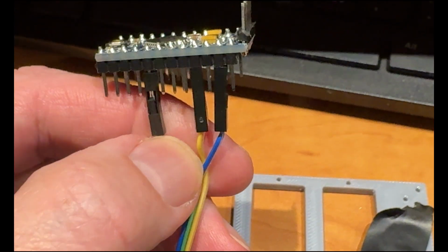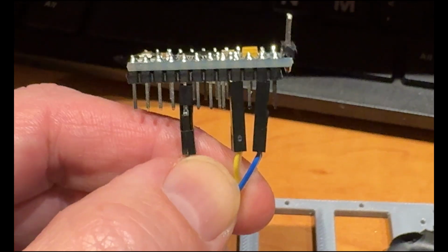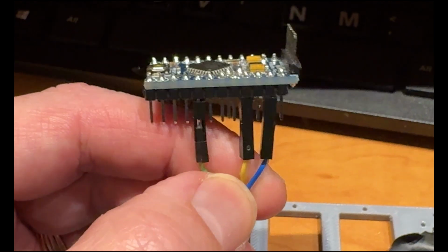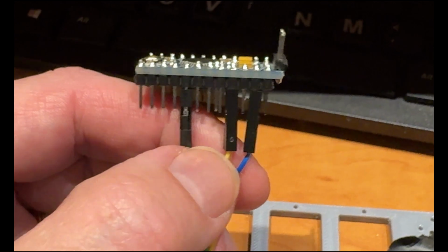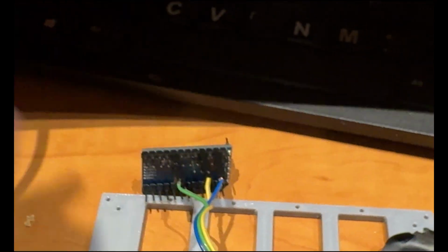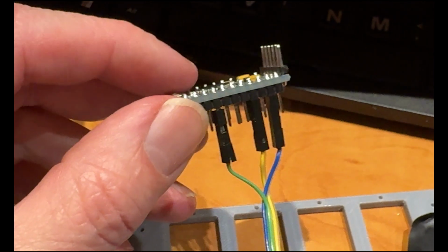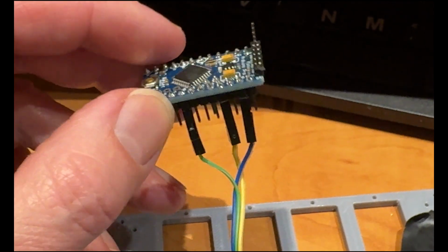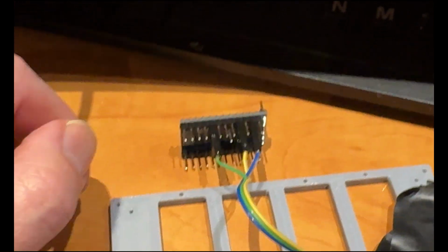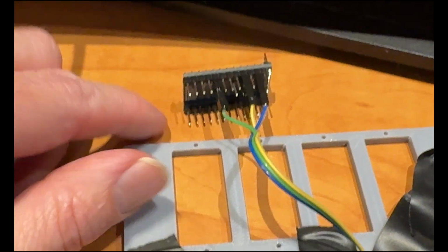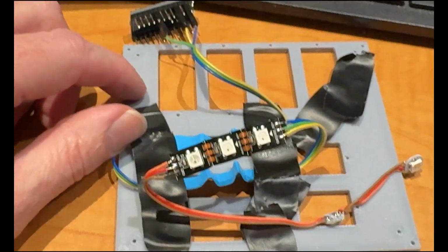And then as far as power, you can get a 4 AA battery holder. AA batteries are 1.5 volts each, and that'll get you to 6. You basically just hook the ground up to the ground and the power to the power, and usually they have an on-off switch, and away you go. So that's what you can use if you want to power these things. You can even use a phone charger, which is 5 volts. Take the USB cord off of that, cut it, and then use the ground and the power, and you can just chuck away the data. So that is that, a poor man's Vader box light deal.